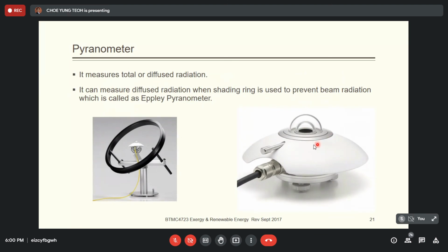And then you can see that this has the sun shield, the white plate over here. First, why white? Why not put another color? Because this plate is connected to the sensor. If you make it black, it will increase the temperature of the sensor. The heat will travel through the plate and then through conduction to the sensor.